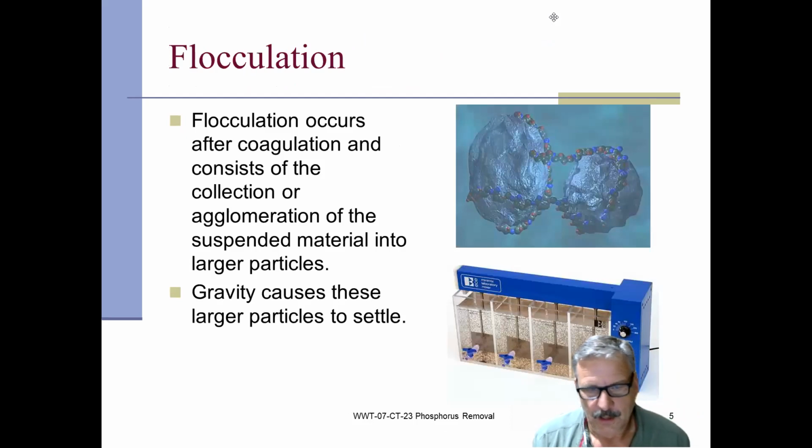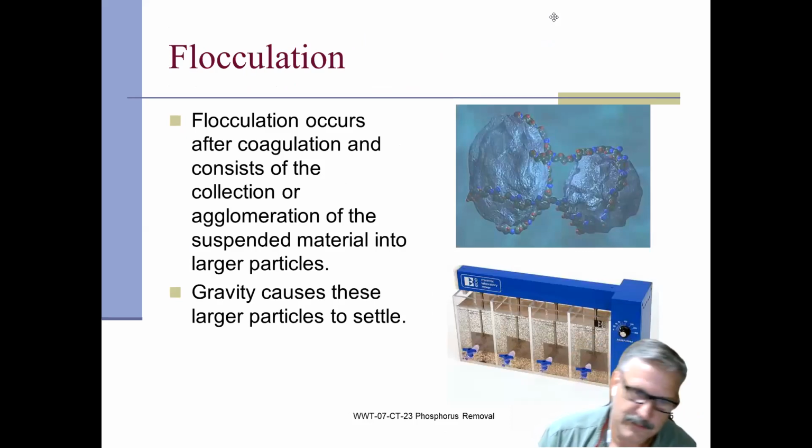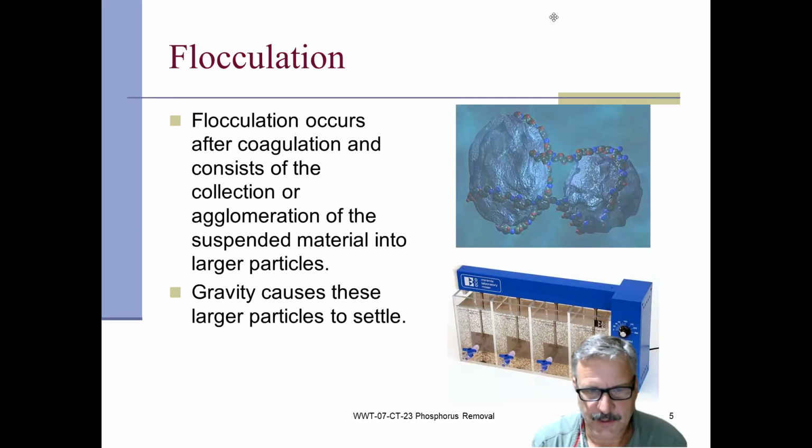We mentioned a little bit about, trying to move my head out of the way, talked a little bit about jar tests today. Just remember, jar tests are usually done in a lab. If you wanted to figure out the dosage of alum, how much alum you'd add, you'd take the same amount of the sample, you'd put it into each one of these jars or tanks in this configuration. You'd inject different quantities of alum into each one and see which one gives you better results. Okay.